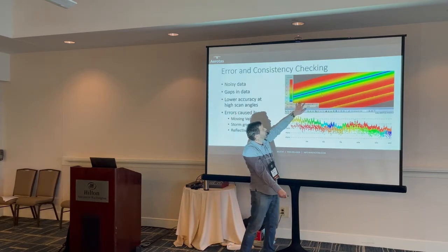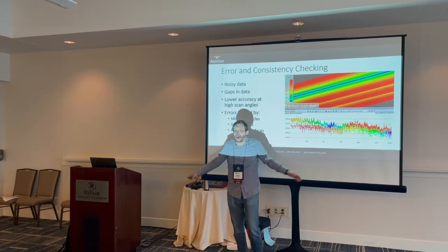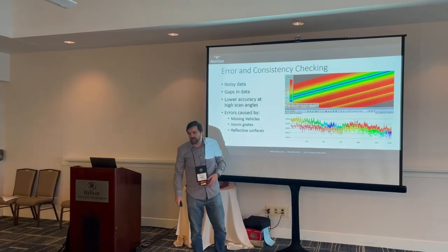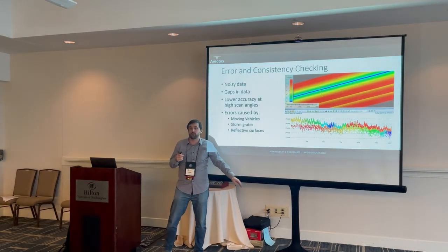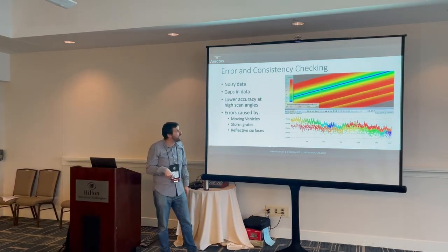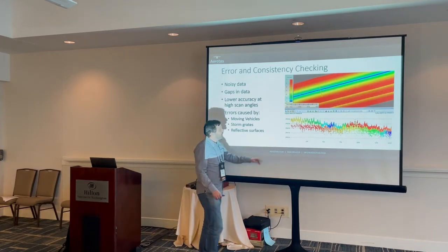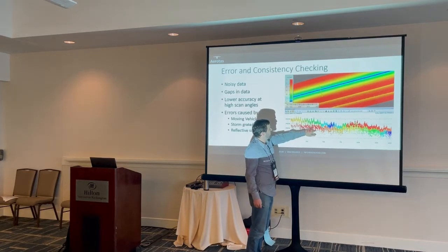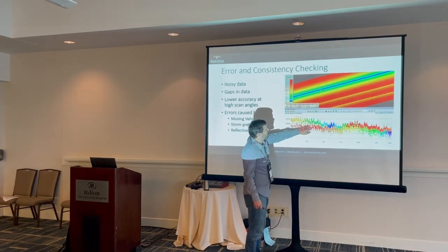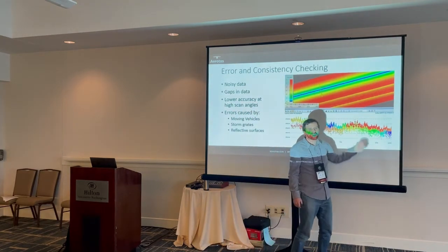And the colors turn from green to yellow to red as that LiDAR scan angle goes up, a higher scan angle. Higher scan angle is going to mean that the laser itself is actually going quite a bit further from the drone. It has longer distances to travel, and it has considerably more noise in it. And what we see on a profile view from some of this is that some of these red ones, the high scan angles, are showing some systemic differences from the medium and low scan angle ones.